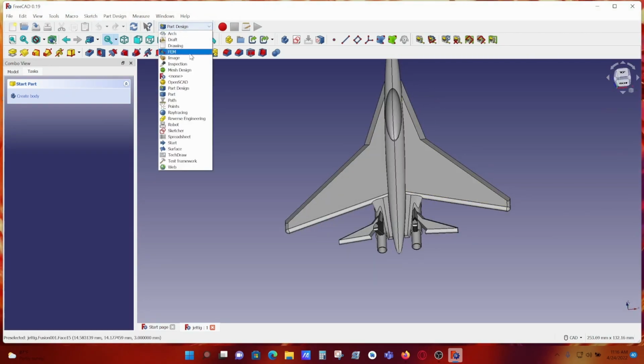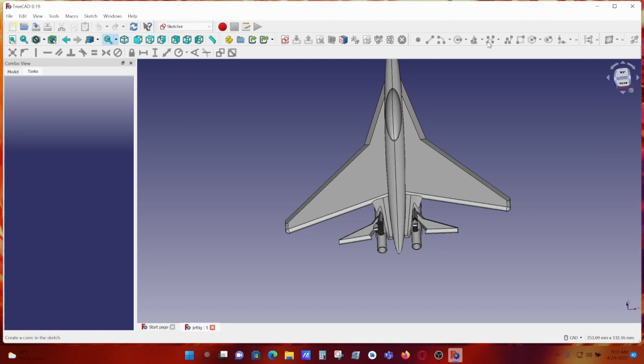And while making these things, I used a polyline tool. What I did at first was use a lot of line tools and combine them using the coincident constraint. Instead of that, using a polyline tool was much more efficient. I saved a lot of time using that.